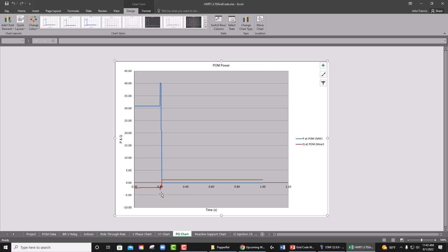The moment that the voltage goes up, we measure it and try to reduce the reactive power, try to absorb more, but immediately we're going to trip because voltage is really high. So keep that in mind, that's happening here too.